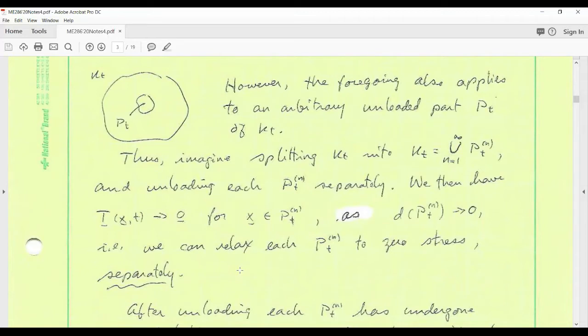And then by mapping, if you have a constitutive equation for the body, mapping that piece back into where it fit before you shaved it off, that would be the deformation. Having the constitutive equation, knowing the deformation, you then know what the stress was before you shaved off that little piece, and that would be the residual stress in the unloaded overall body.